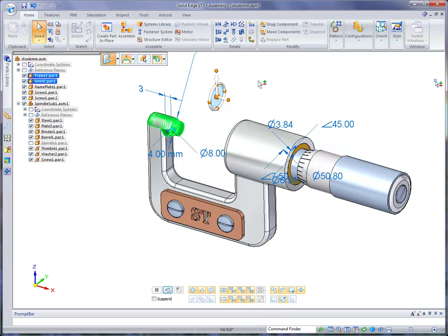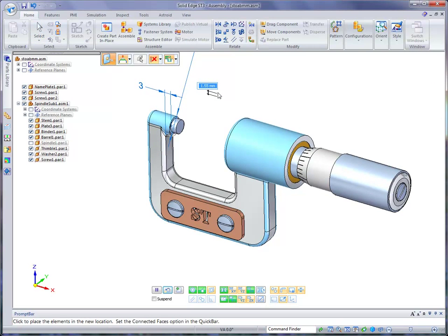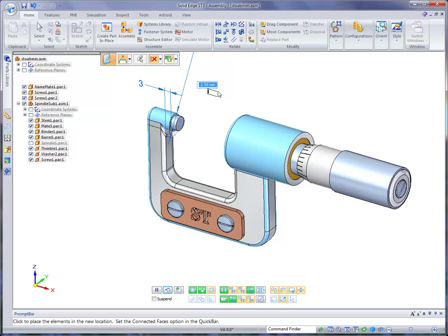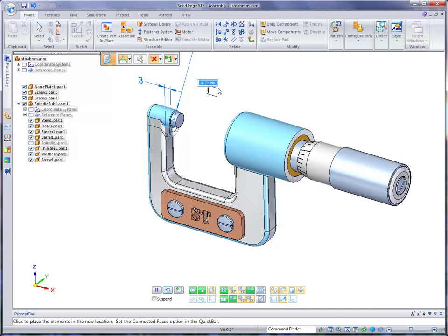Now at that point, I'm going to click on the primary axis, and you'll notice that Solid Edge will automatically go into a move mode, and as I gradually move my cursor up, you can see the value field is changing. Now notice down below the Live Rules. Notice the Live Rules that have turned green. Those are the Live Rules that are being applied to this model as I move these parts.